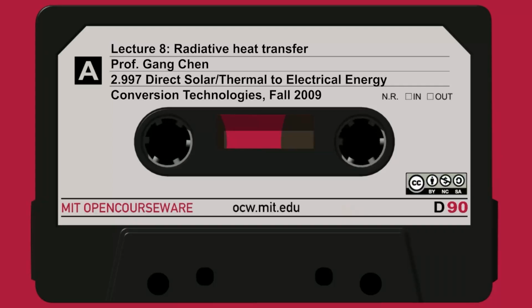So the solar thermal engine is always a fight between losing heat by radiation and the Carnot efficiency. The thermal engine wants to operate at higher temperature, but your surface doesn't want to operate at high temperature. Now if you go back to even the ideal absorber, meaning a 1 and 0 selectivity spectrum, you push to higher and higher temperature depending on your concentration ratio.